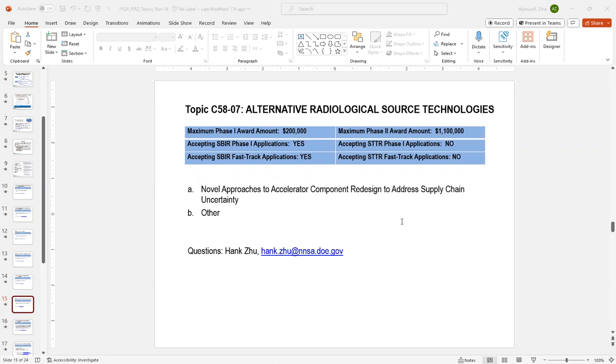Yeah, so I would say that the endurance of the UAVs is a big consideration. I would say you should have at least 15 minutes of operational time, air time, with your payload. I mean, fully loaded with your UAV.